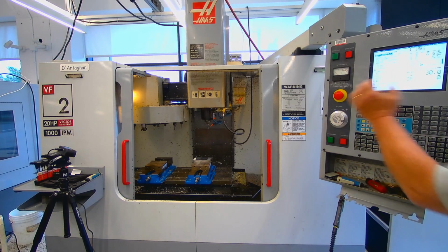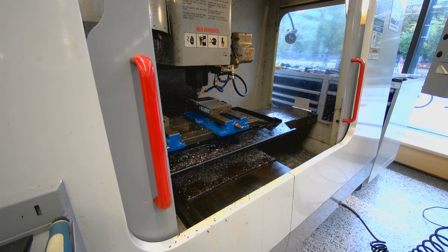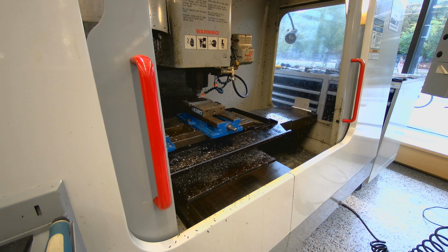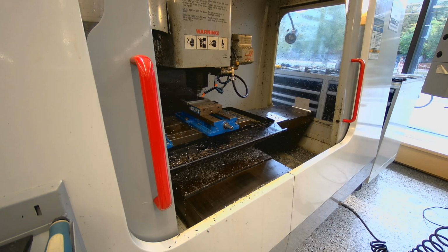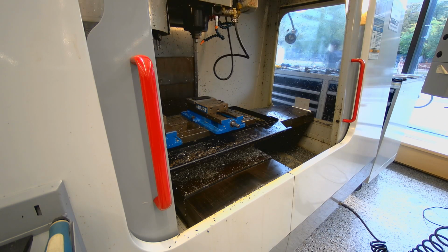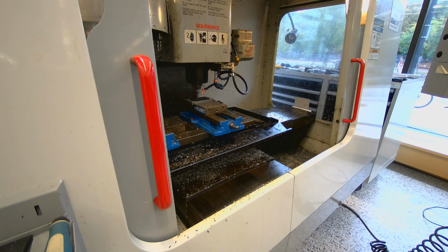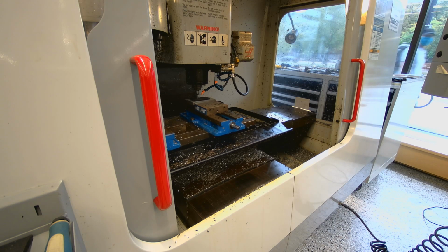So, go get tool number 1. This is that finished mill bore. Go to depth, walk out the radius, cut a circle. Go get tool number 2. See the ramping move to get to the Z depth? And now the pocket concentric circles till it reaches the boundary.